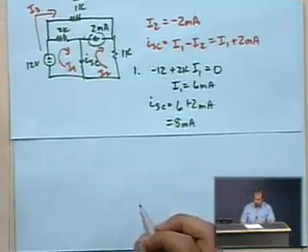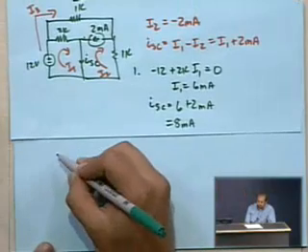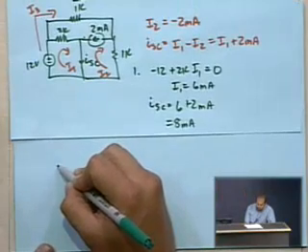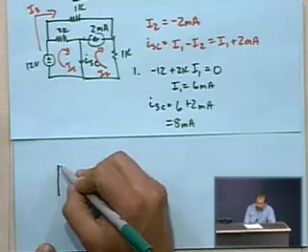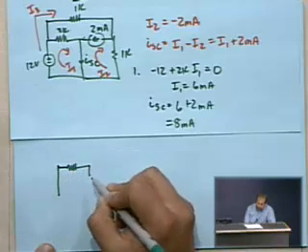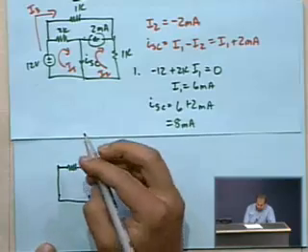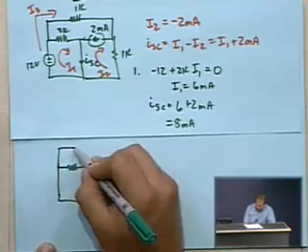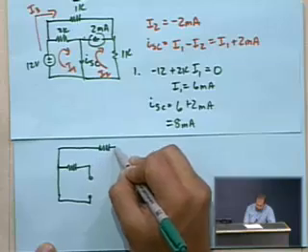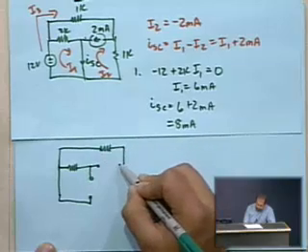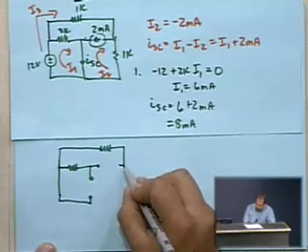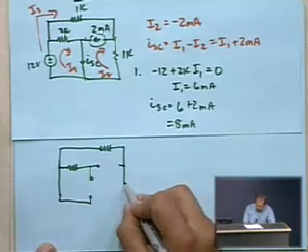So let's pull the circuit on so we can see at least a little bit. We start zeroing out the sources. So we short circuit the 12 volt source. We've got the 2K resistor. We're looking at it from these terminals. We've got the 1K resistor that goes along the top here. This gets opened. And then we've got the 1K resistor here.